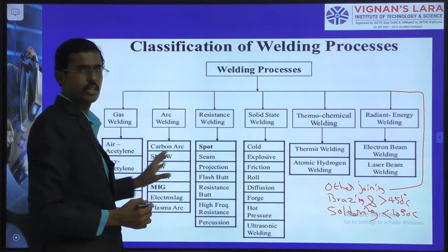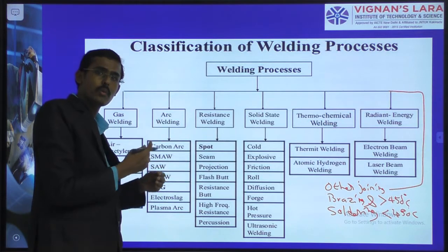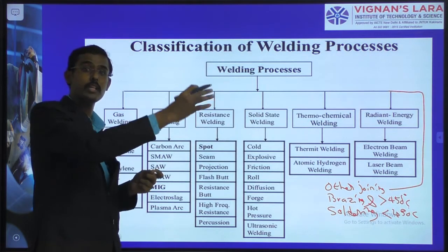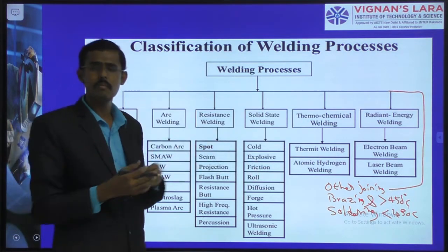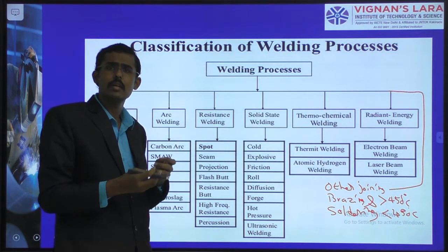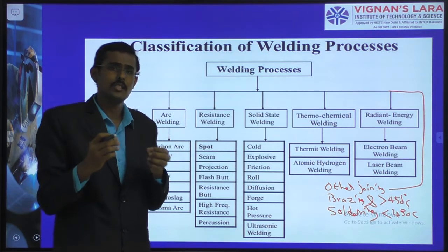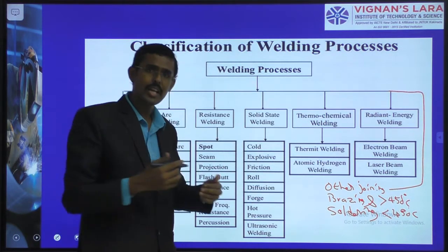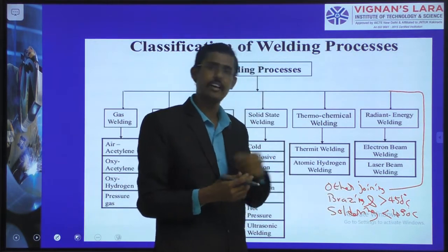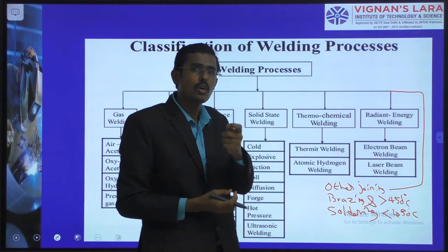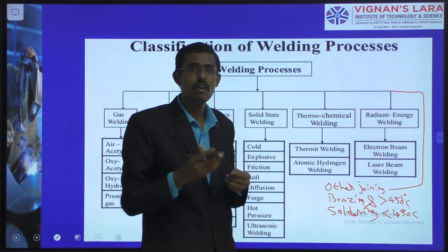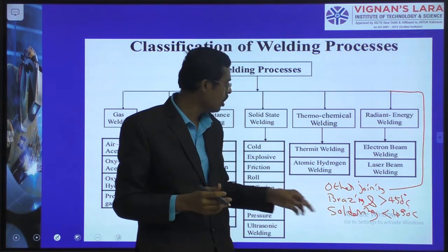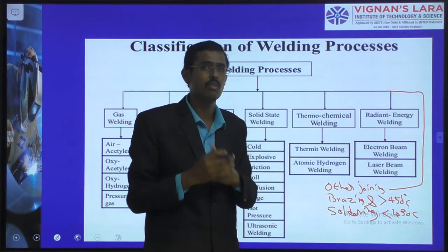So far, in the arc welding process, we have gone up to the melting point, around 1500, of the materials, and in the solid state welding methods we went up to plastically deformable conditions, around 1200, and now we are coming down to a low level of less than 500. Soldering is used for electronic components, chipsets, and green boards; we have seen it at our homes also.